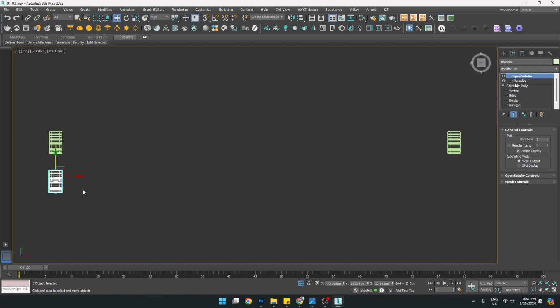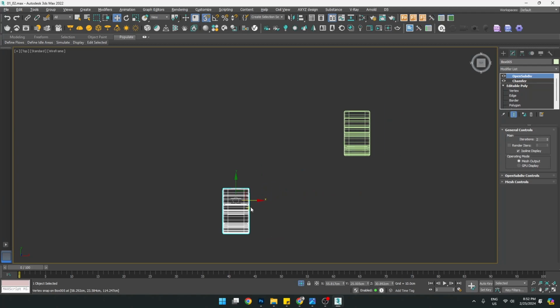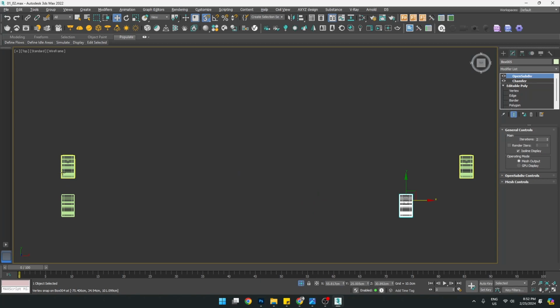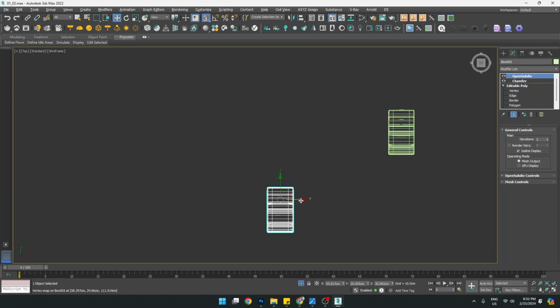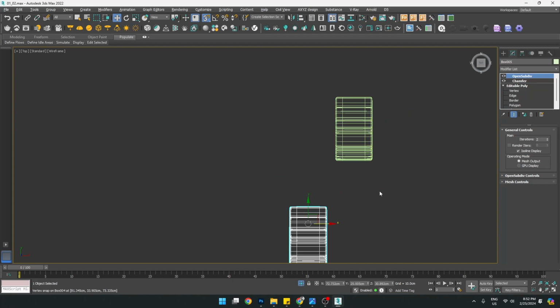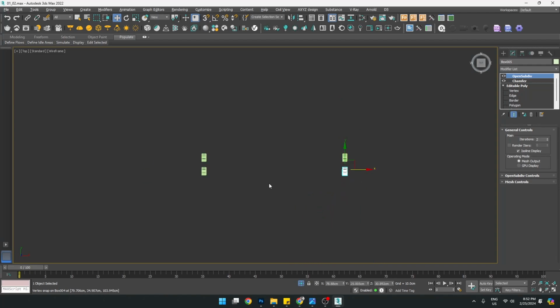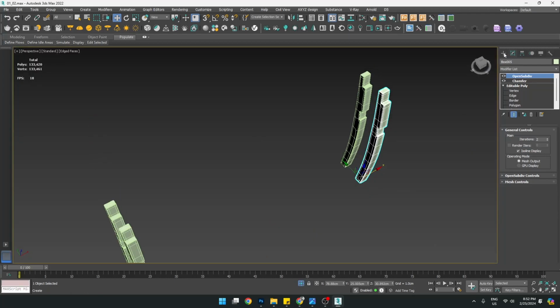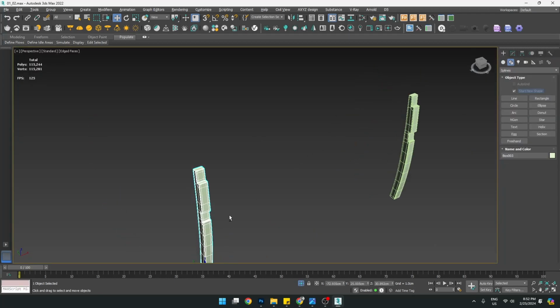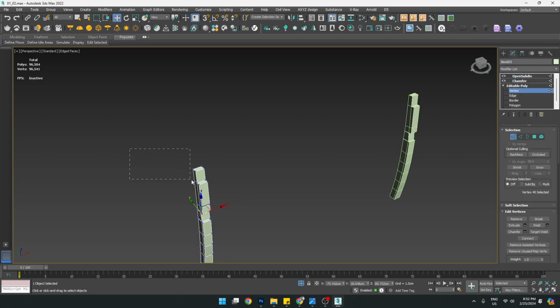Now it is already instanced, but you can't see it unless you move it, because it cloned based on the pivot and it was sitting on top of the original object. Now you understand why I kept this copy. Now we can snap it on the edge or any of the vertex here. We just snap it here. Now if you check, whatever we do here will get reflected over there.